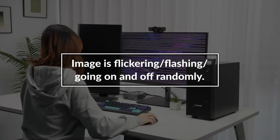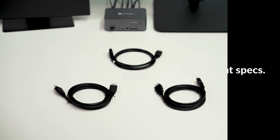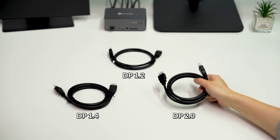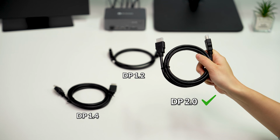Image is flickering or flashing or going on and off randomly. Number 1. Firstly, use cables of good quality and right specs. Make sure your cables are able to handle the images you need. Try a higher standard or a shorter one, because long-distance transmission can cause problems.